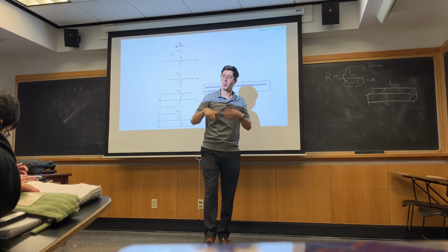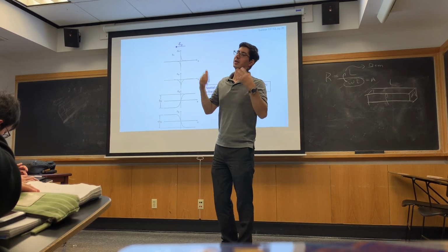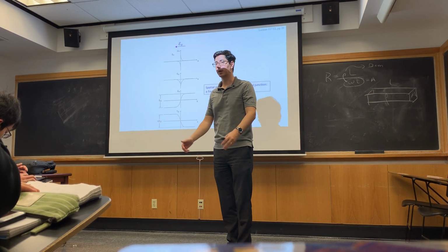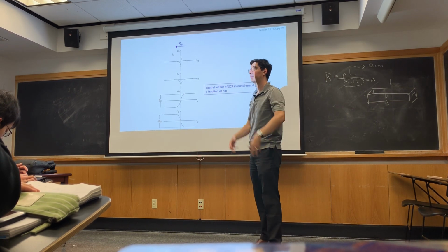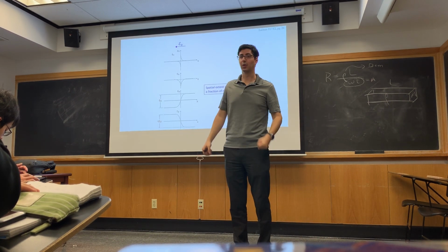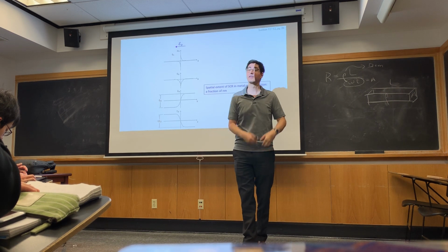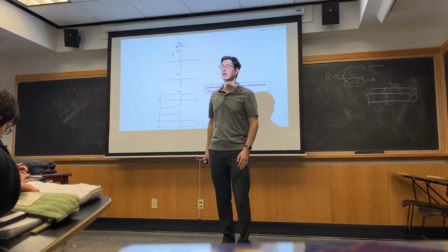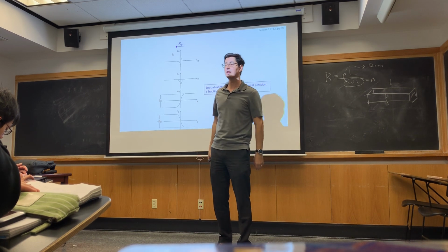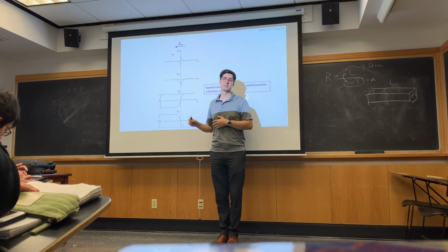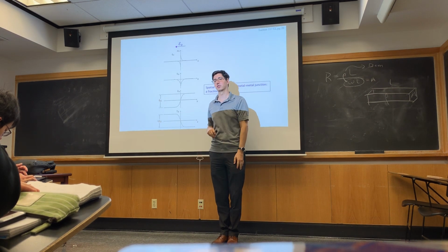Why is that? Well, once again, in metals, they only have charge at their surface, right? Where is that coming from? It's coming from the Debye length of a metal, right? Electric fields can't penetrate. Why can't they penetrate into a metal? Because I have so many free carriers in a metal that they just screen. And so going back to that analogy with the p plus n junction, you can think of a metal as a p plus plus plus plus plus plus junction, right?